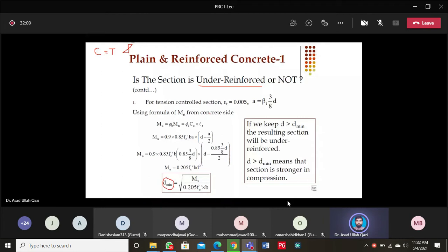Definitely serviceability will guide us, the serviceability requirement, that this must be the minimum h to control the deflections. So ACI has given us in chapter 9, in tabular form against various end conditions and steel grades, the minimum required h value. So that is actually the first check which we are going to make before finalizing the cross-sectional dimensions.